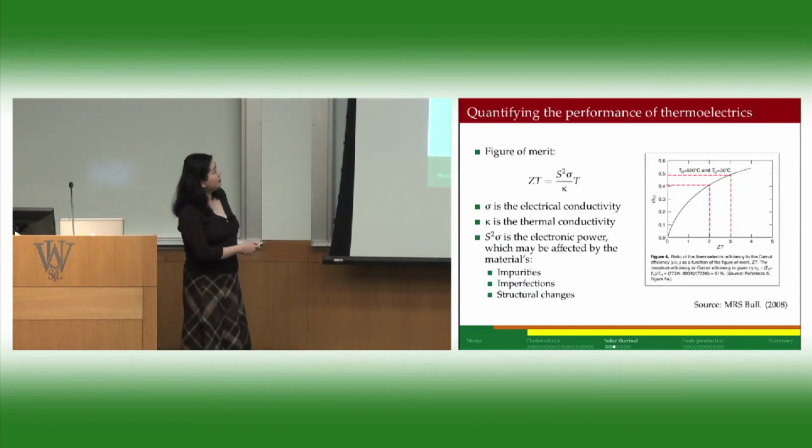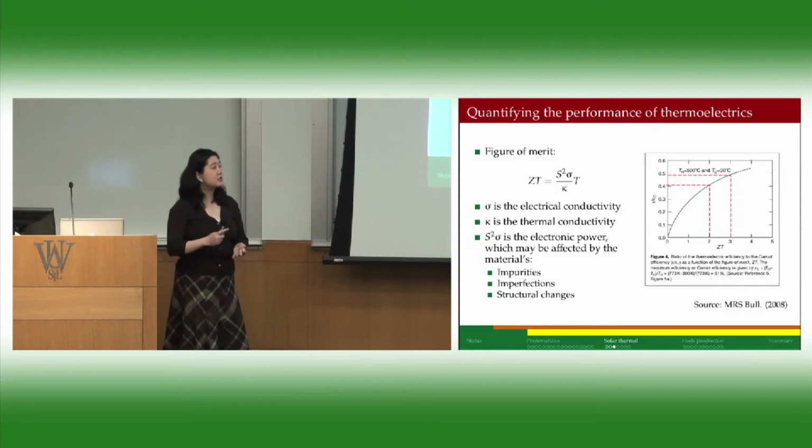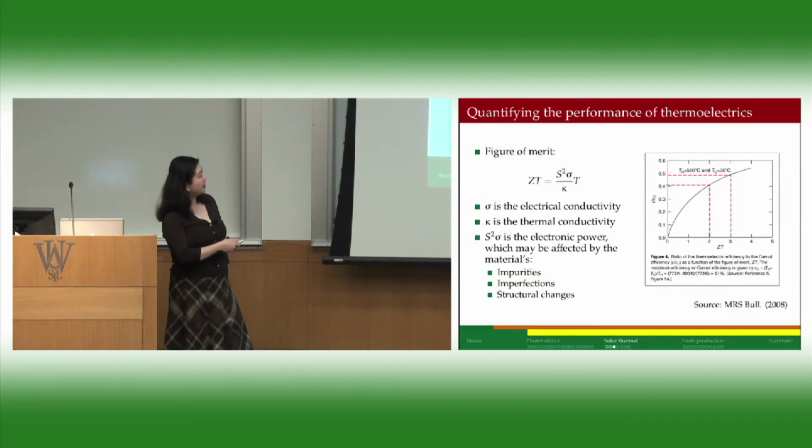And more importantly, we can calculate a figure of merit that's related to the efficiency of this thermoelectric. So again, we talk about efficiency of photovoltaics, of photosynthesis, now thermoelectrics. For the ZT value, which is the figure of merit, you can figure out the efficiency compared to the Carnot efficiency. You can plot that here. But this is a pretty easy thing to calculate, in theory. It's a little bit complicated, but the terms are pretty easy.